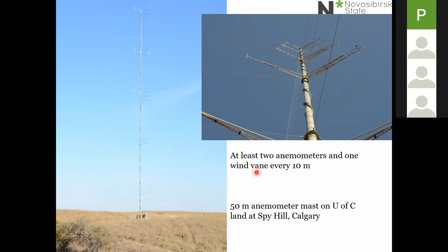So if I'm involved in a wind farm project, the first part of that project would be to put up an anemometer mast, and maybe 3 anemometer masts, on a potential site and measure the wind regime for about a year. And that's really absolutely necessary as part of the wind resource assessment process.